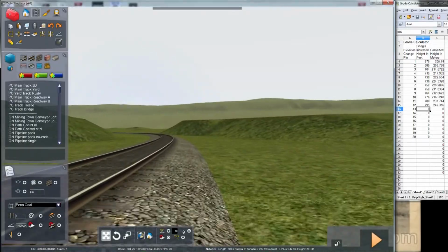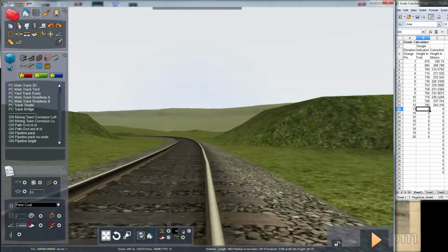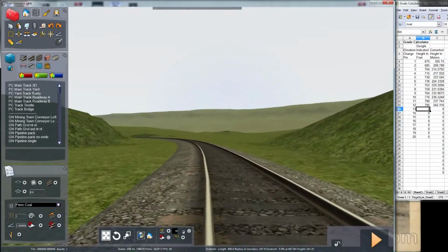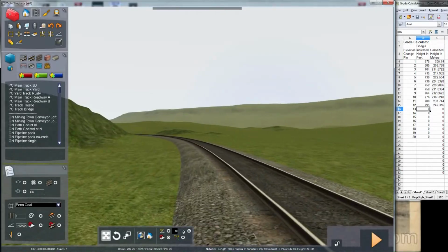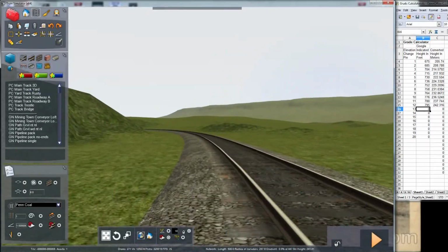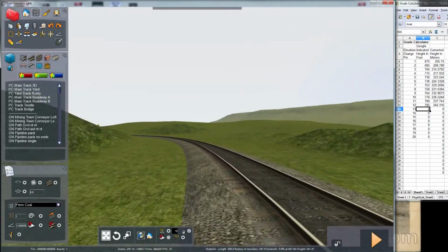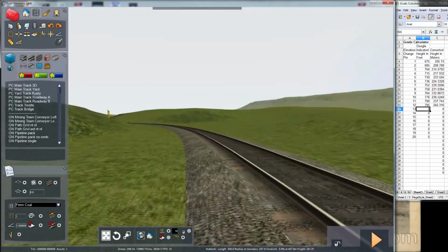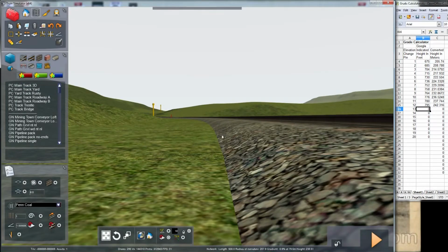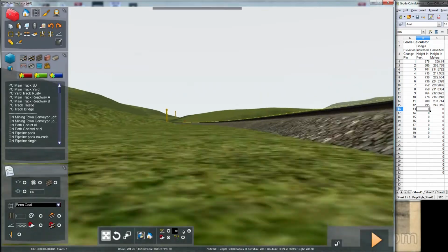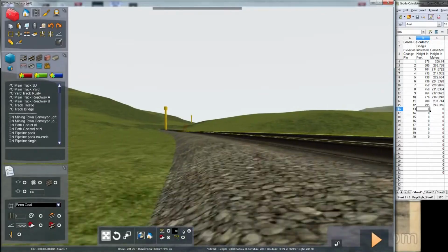As I told you earlier, this is one of my previous tutorials. The old track people, when you're laying track in the manual methods, when you're not using a surfacing machine that uses a laser light, like the modern track people use, in the old days they would carry a cushion, and the gang leader or the foreman, or maybe one of the other men, if they were feeling generous that day, would throw a cushion down beside the rails and sit on that cushion, and they would lean their head down and sight down along the top of that rail, and they would level the track.